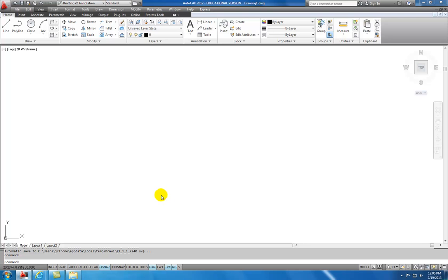So let's take a look at drawing lines. If I select the line command, I'm going to be prompted for the first point. Now my heads up cursor is on, and that's on because the DYN value is selected to be on. And what that will do is give me a point in space relative to my origin, and my origin is where my X and Y plane are. So I can click a line, and as I bring that line out, it gives me somewhat of a rubber banding effect with the length of that line.